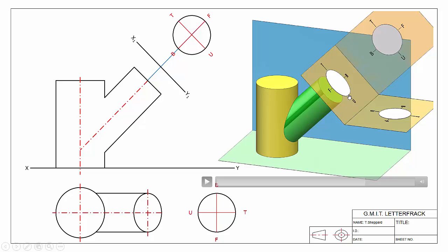And you can imagine that's because the underside there ends up like so. So you can see the top ends up further away. So that's the reason why that's orientated. And that really does come into one of the most common mistakes that students make. They mislabel the top and the bottom, and then when it comes to drawing in their object, they don't line up. So that's the top and the underside like so.